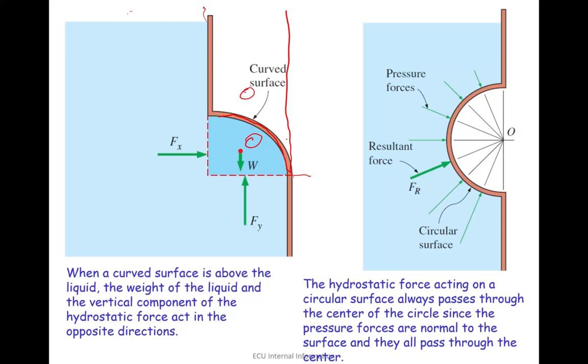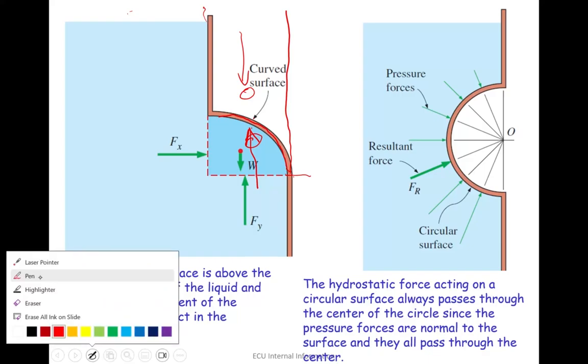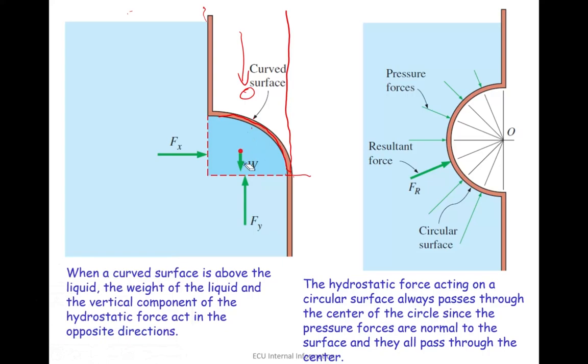So we can estimate the vertical force, but because we imaginarily assume the water is on the right-hand side, we need to pay attention to the direction. The direction should be upward. This is one simple way of estimating vertical forces if you don't want to go through more complicated calculation, providing that such an assumption can be made.